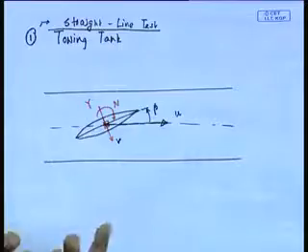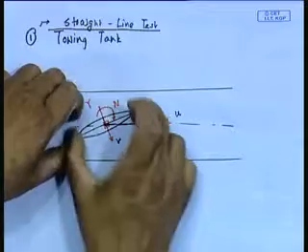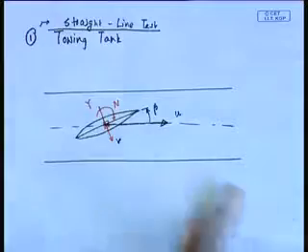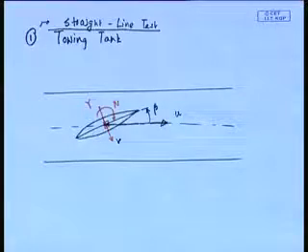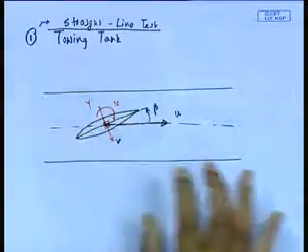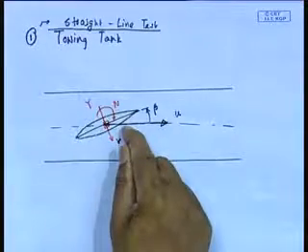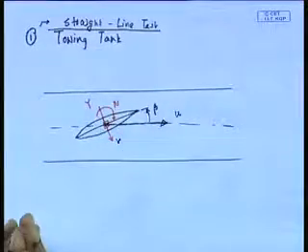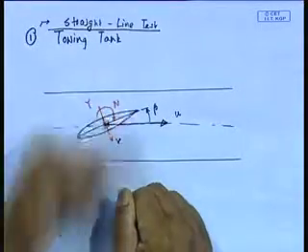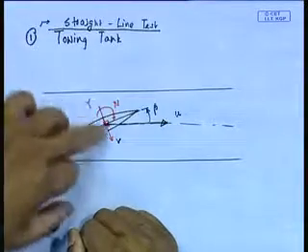See, in a resistance test, you have a model that is towed and you measure the X force, that is what you are doing, right. What do you do in a resistance test in a towing tank? You have a model, you tow it along a straight line and measure the X force with a dynamometer. Here, in this first test, you do the same thing, but you now tow it at an angle of attack beta, and you measure Y and N with a dynamometer.